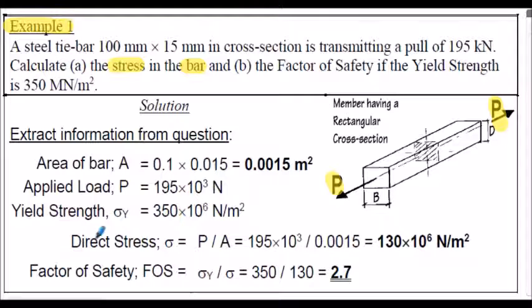Here is the direct stress calc shown here, which is the force applied divided by the cross-sectional area of the member. Engineers are generally quite proficient at solving such static problems, but sometimes have difficulties in considering and analysing dynamic problems. A static problem is a balance problem, where with this particular bar, force at one end is balanced by equal and opposite force at the other end.